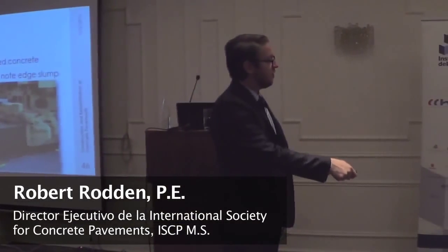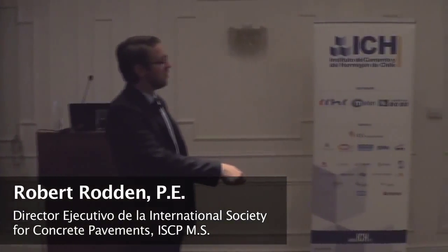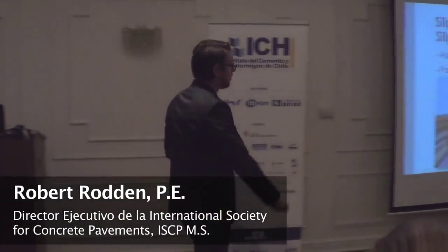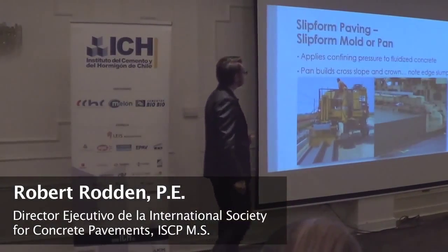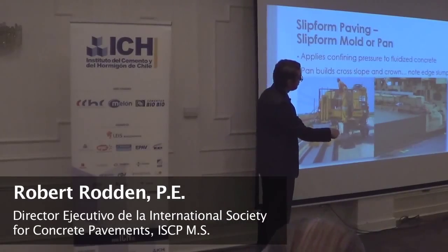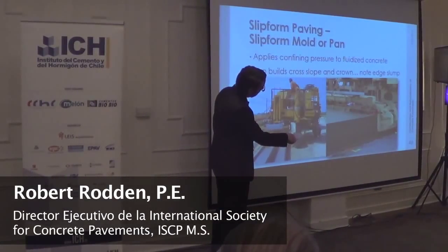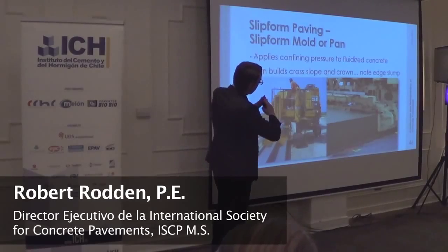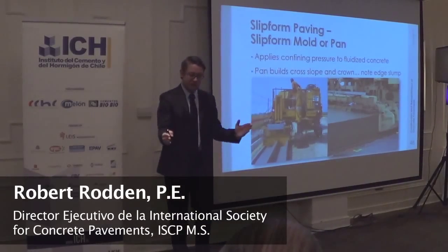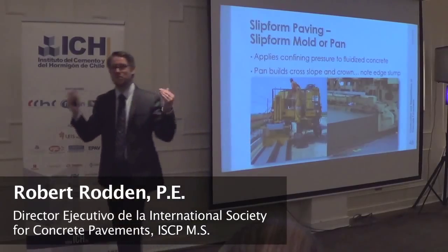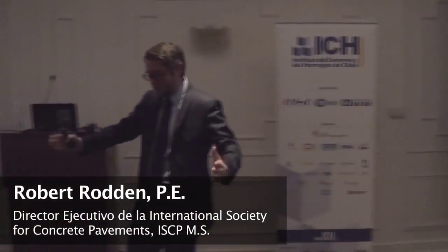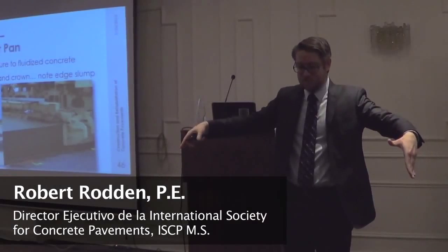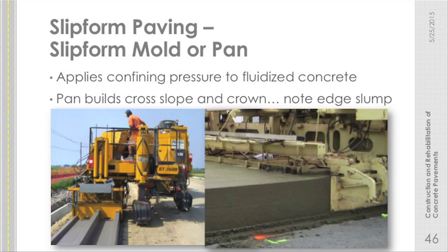You can see here they're making a utility channel, the photo on the left. We can slip form very wide and thin too. We just change the mixture, we change the equipment, but we can make concrete stand up very, very tall. So this final form, this one that creates that angle, that pitch there, and that angle in, also pinches the concrete in just a little bit in every direction. So the side forms are pretty much parallel. This tapers in just enough to apply a final compression or final consolidation on the concrete.